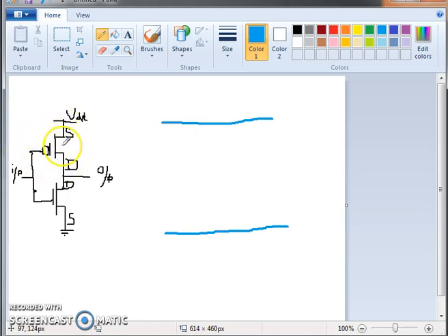Now to create a PMOS transistor, it's P diffusion, yellow color. So you have a P diffusion which is yellow in color. To form an NMOS transistor, it's N diffusion, which is green in color. And formation of a transistor is poly crossing diffusion. So this is your transistor. Select red color for polysilicon. Poly crossing yellow diffusion creates a PMOS. Poly crossing green diffusion creates an NMOS transistor.